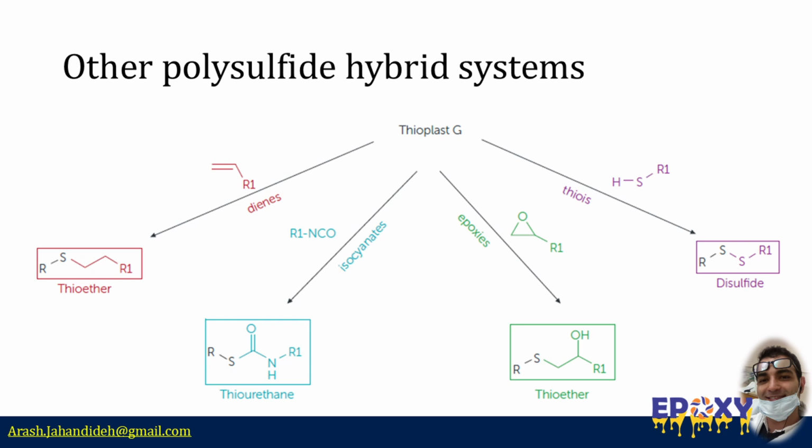A key feature of liquid polysulfides is their thiol end groups, which exhibit strong reactivity toward diisocyanates such as 2,4-toluene diisocyanate or TDI, diphenylmethane 4,4'-diisocyanate or MDI, and multifunctional liquid isocyanates. This reactivity enables the formation of hybrid polymer networks with enhanced performance characteristics. Replacing traditional hydroxy-terminated polymers with liquid polysulfides in these hybrid systems imparts the cured materials with significant advantages.